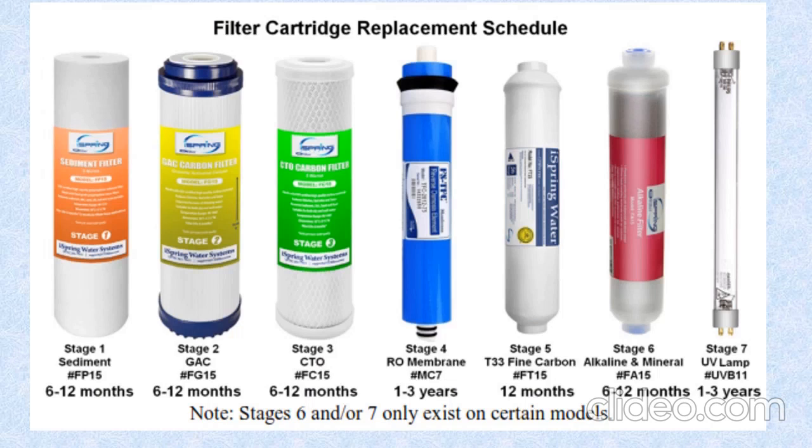So our RO unit may have a maximum of 7 stages. It depends upon the water which we require. Stage 1 is the sedimentation. Here it is a cotton roll, which is kept outside the unit for pre-filtration of water to remove the dust particles, everything. And next, stage 2 is GAC, that is granular activated carbon, which is used to purify the water.